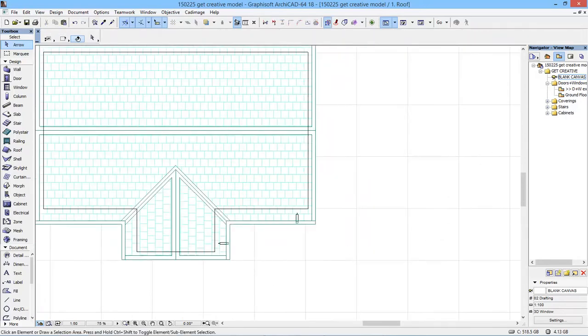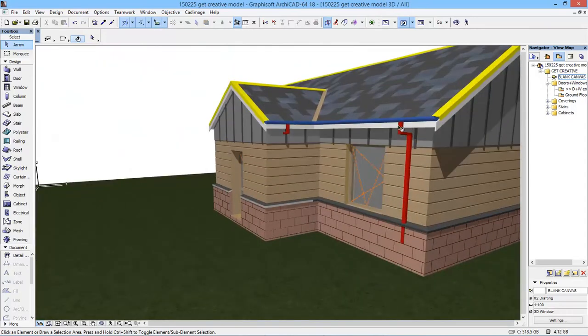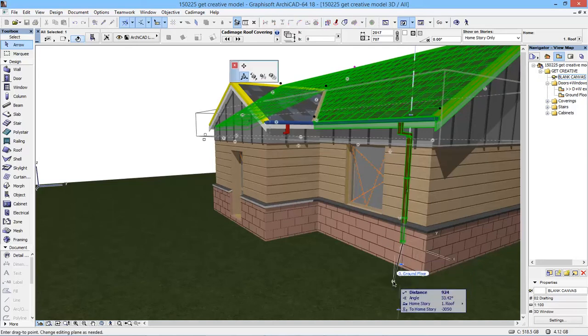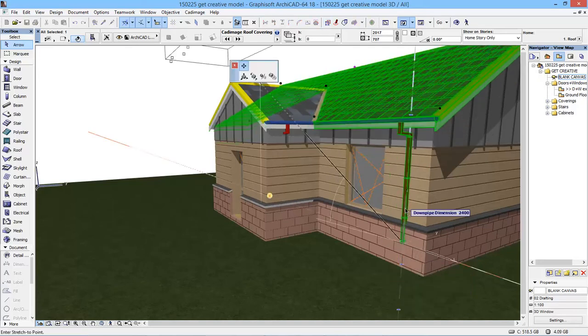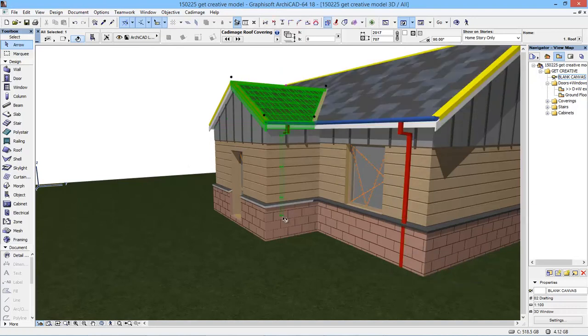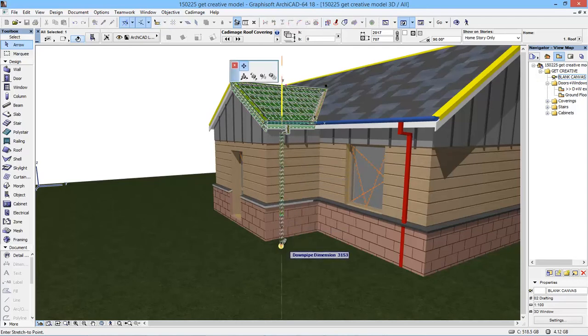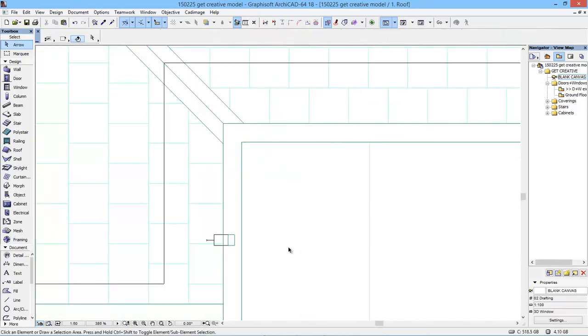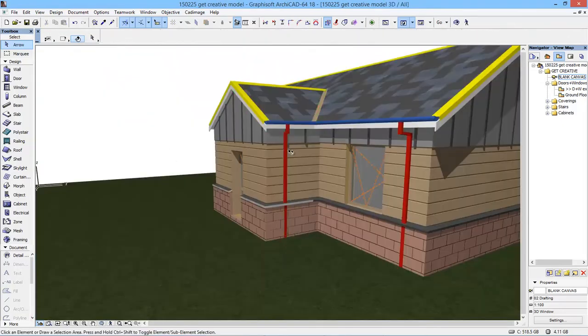And if we just look at 3D again, you can see I have cunningly made these into concealed downpipes. So I obviously haven't quite got the offsets set properly, but the other thing you'll notice, we have to just set the height. So all we do is we pick it up and we just stretch down to ground level. The same on this one. I know it's hidden. We'll go back and sort that in a second. So we just bring that down to there, drop back to 2D, bring it forward until it hits perpendicular. And you can see now it's almost there.